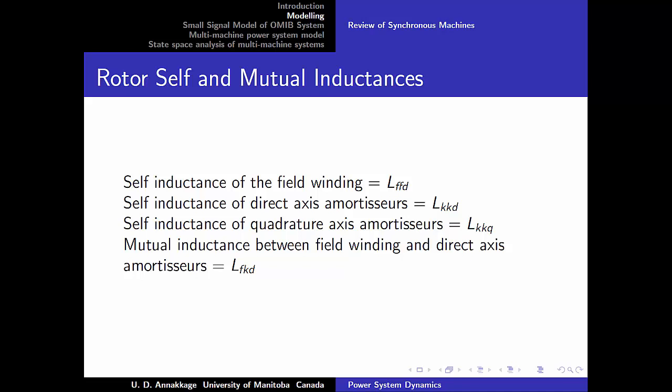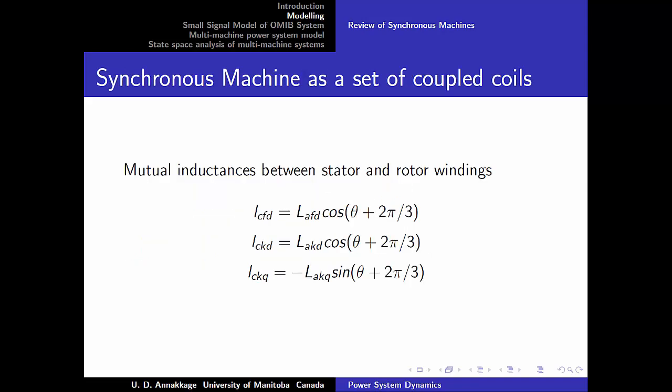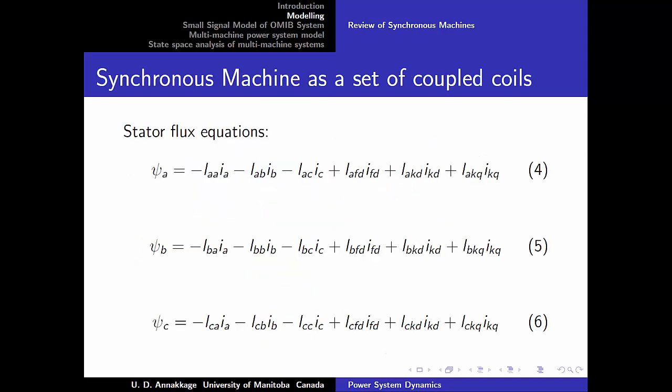Now let us focus our attention on the voltage and flux equations that we presented in slides 2 and 3. So let's go back to slide number 3. It is clear that the analysis of the behavior of a machine becomes very complicated because we already learned that some of these inductances are functions of theta. And this is because theta, the position of the rotor, is time dependent.